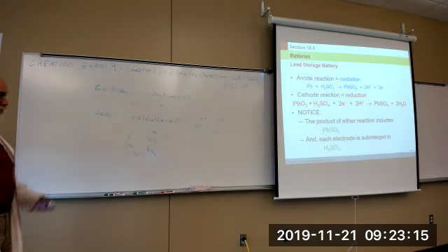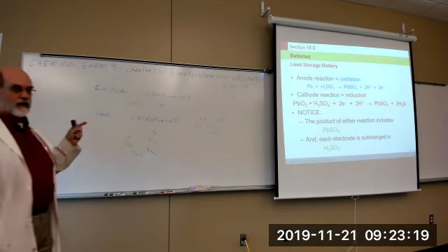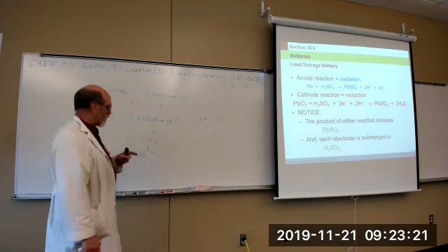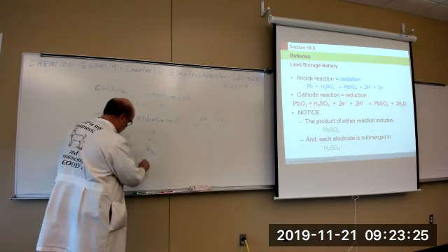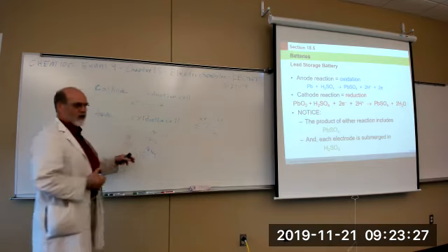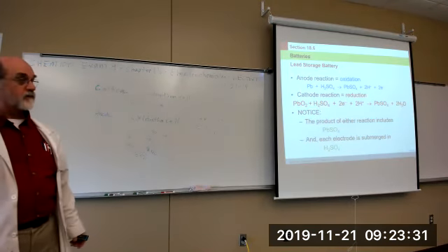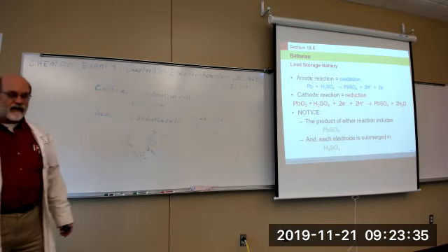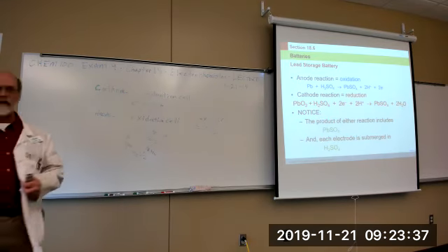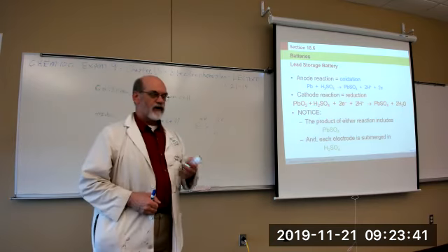So if you've got a lead acid battery that will not charge again, well, 2 things could go wrong. It could be sulfated out, or it no longer has sufficient concentration of acid to complete the reaction. Now, the batteries we have in our cars these days, and some lead storage batteries that are used in other pieces of equipment, are sealed.